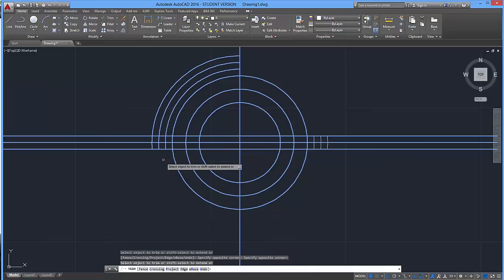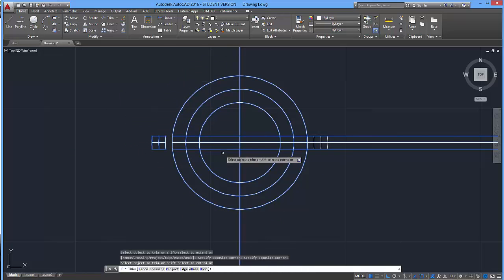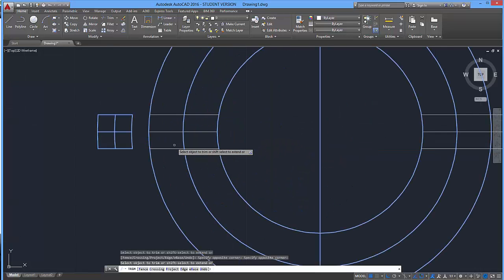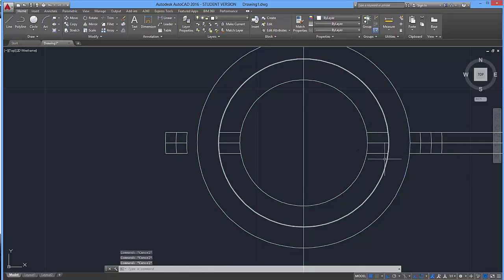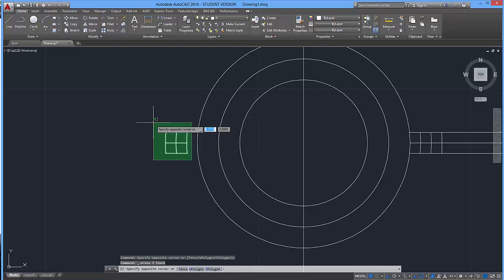I'm going to try to speed this up a little bit. And you're going to notice that if I click and select, I can mass trim at the same time. Now it doesn't work for everything. There are always those somewhat stubborn lines that may slow you down, but in that case just press escape a few times, select them, and just use the delete key on the keyboard, and you're going to get rid of them right away.